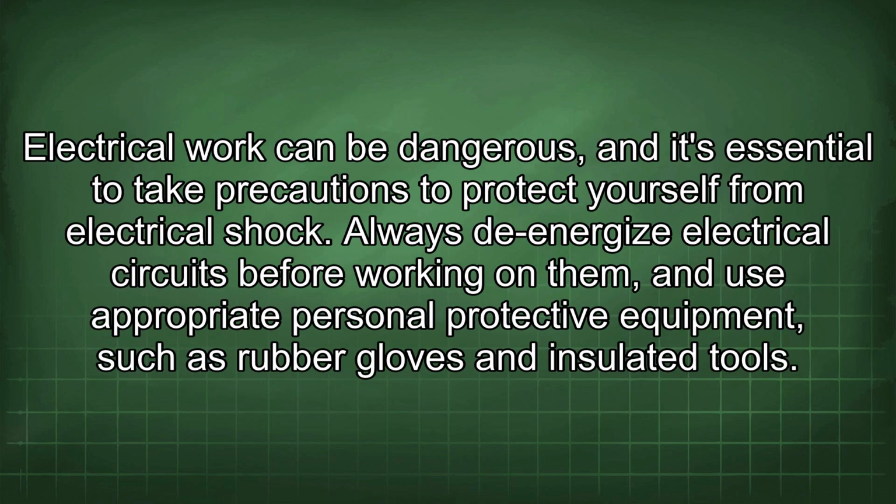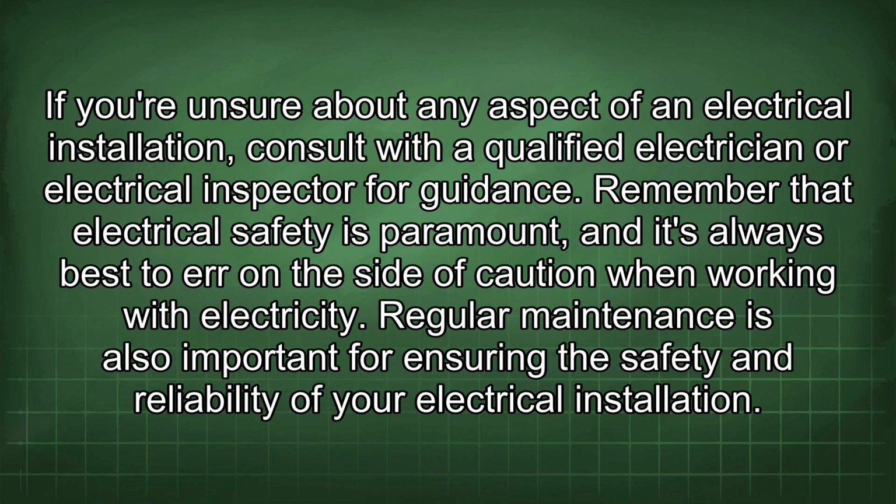Electrical work can be dangerous, and it's essential to take precautions to protect yourself from electrical shock. Always de-energize electrical circuits before working on them, and use appropriate personal protective equipment such as rubber gloves and insulated tools. If you're unsure about any aspect of an electrical installation, consult with a qualified electrician or electrical inspector for guidance. Remember that electrical safety is paramount, and it's always best to err on the side of caution when working with electricity.